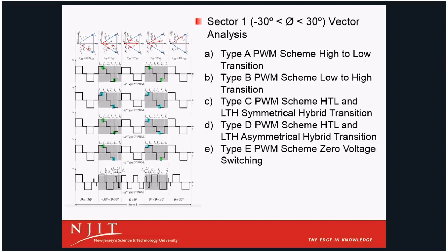So we'll discuss more about the benefits of each different switching technique later. And the biggest thing there is the losses are actually different between the two. So even though the switching from an active vector to a zero vector, the losses are pretty much the same no matter what scheme you're using. The switching from high to low is the bigger difference in this case, and we'll discuss that here.